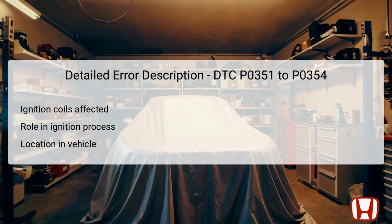The ignition coils in the Honda Civic 2011 to 2015 are vital for the ignition process, as they convert low battery voltage into the high voltage needed for spark generation. There are 4 ignition coils in this vehicle model, 1 for each cylinder. Each ignition coil is located on top of its corresponding cylinder, making them accessible for inspection and diagnosis. The engine control module, ECM, oversees the operation of these coils, ensuring they are functioning properly. When a malfunction occurs, the ECM records the error by activating the DTCs.